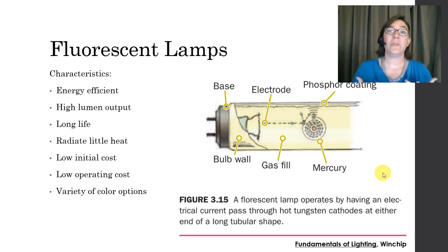All right. It used to be that fluorescent lamps were very, very cold. They were very cold and blue, greenish lights. And also you couldn't control them. You couldn't put any kind of dimmer on them; they were basically on and off only. All right, the technology has improved. There are a wide range of colors, color rendering, okay, and you can now get high color rendering fluorescent lamps in warm tones with dimmable ballasts.